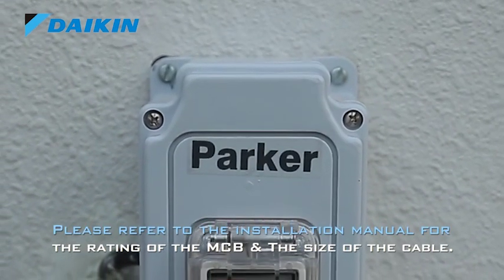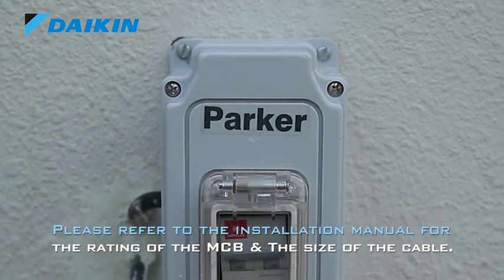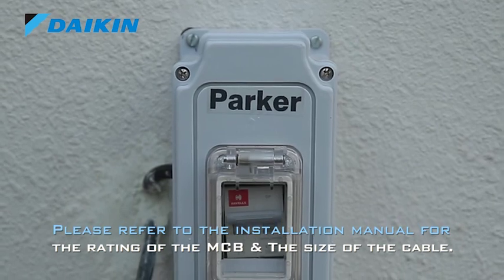Ensure that the rating of the MCB and size of the power cable should be as per the specification mentioned in the installation manual.